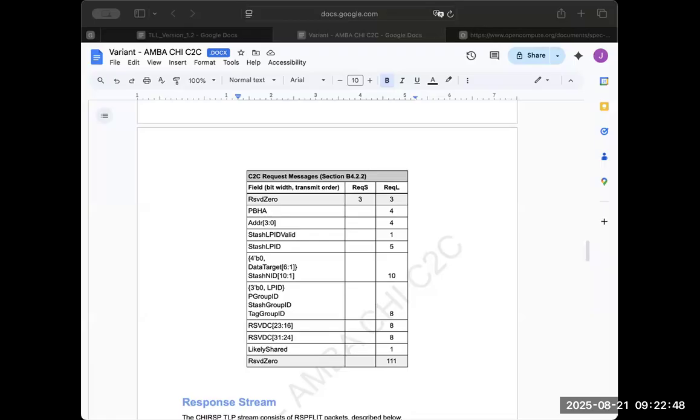yeah, again, those credits that are communicated in either of those positions pertain to the link, and it's effectively the FIFO size in a link controller. But I think the CHI C2C credits would be whatever FIFO size you have in the CHI C2C itself, right? Otherwise, I think we're talking about two different FIFOs and two different layers that are counting FIFOs differently. If they were all one controller, you could merge them, but I don't think you can make that assumption. Let me share something else here.